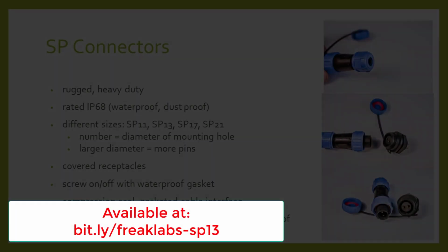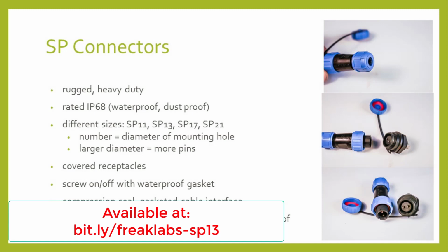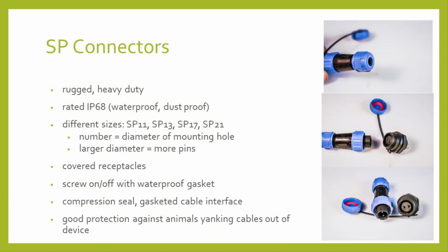The SP connectors are heavier duty connectors than the Aviation GX connectors and are IP68 rated, so are waterproof. The different sizes relate to the diameter of the hole that needs to be drilled out. The larger the diameter, the more pins the connector can fit.